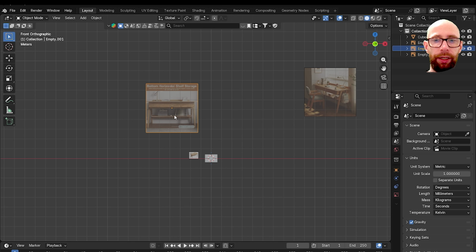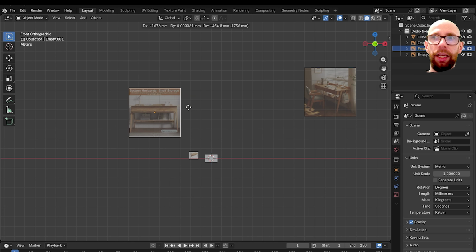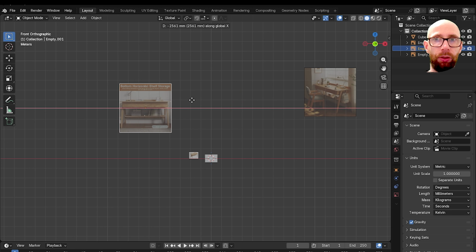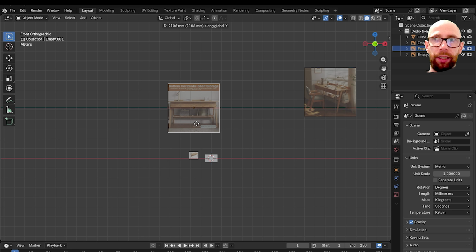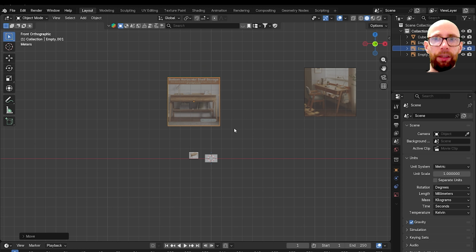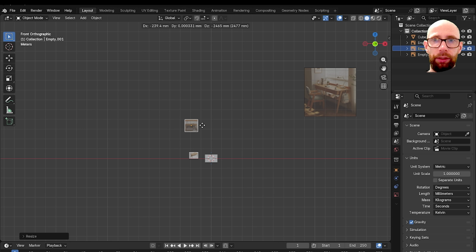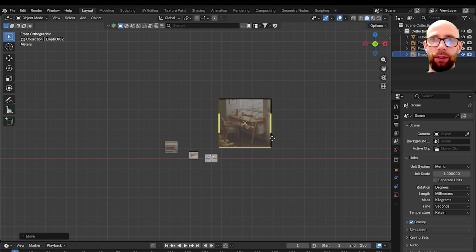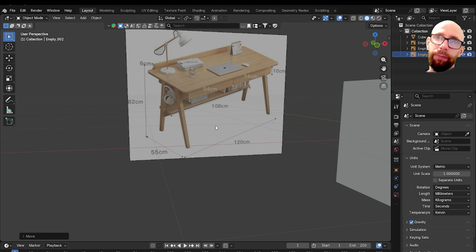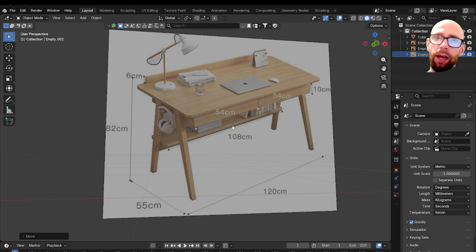So remember, I'm clicking on it, hitting G to grab it. If you want to move it just left and right, if I press G and then press X, it will lock into that axis. Same if I do it and press Z, so G and Z, it will always lock it. But for now, I'm just going to move it down to size, just so I can see them there. Okay. Now we don't have that little thickness there, but that's fine.